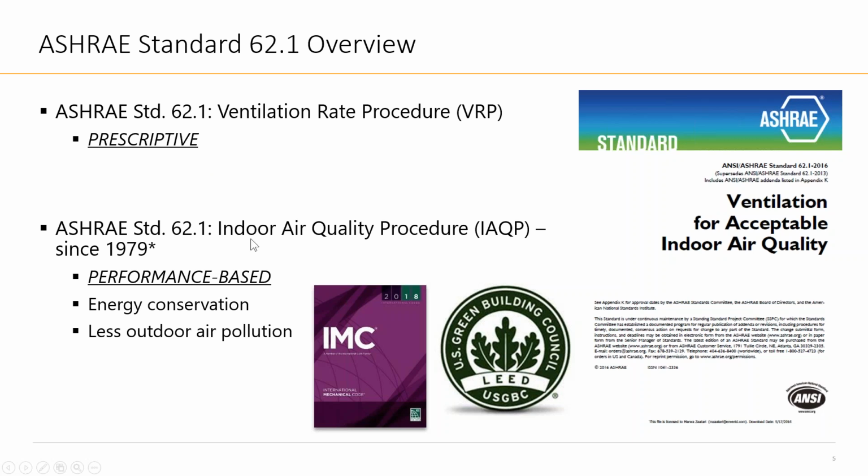The second procedure, which I'm a big fan of, is called the Indoor Air Quality Procedure, IAQP. It has been in the standard since 1979. It's a performance-based approach, and if designed properly, it will lead to energy conservation and at least less outdoor air pollution. One more benefit is maybe acceptable indoor air quality or enhanced indoor air quality, depending on your project goals.